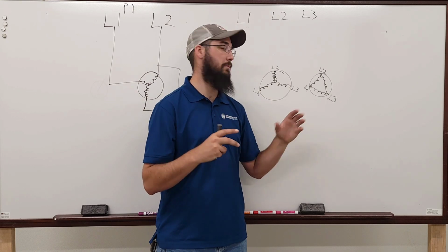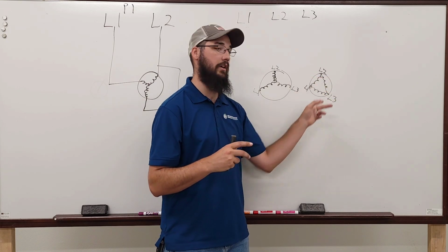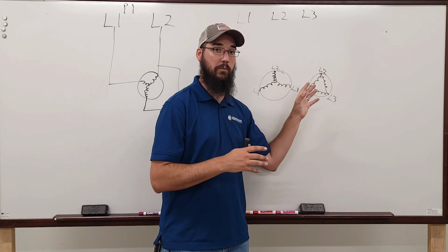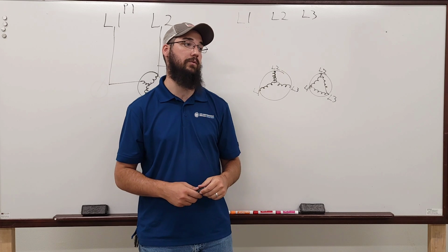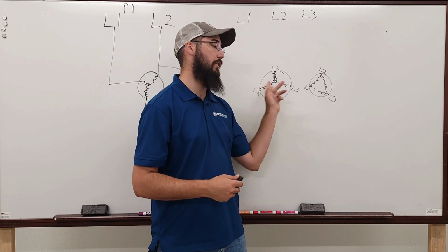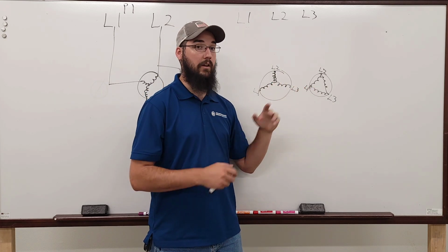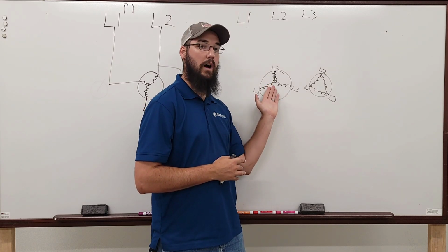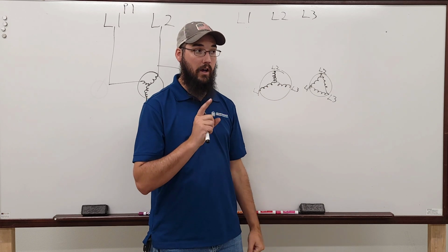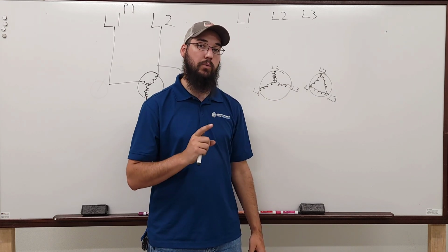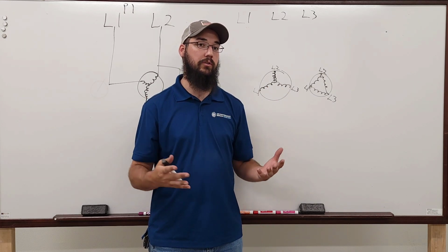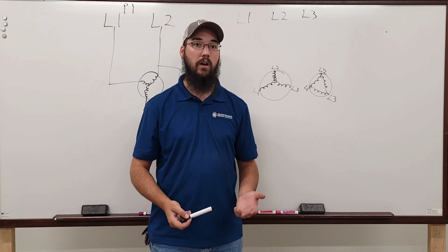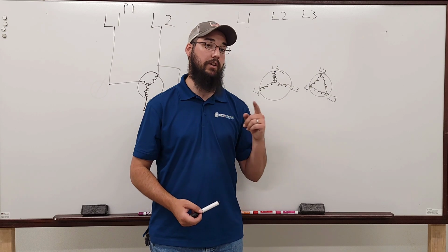So the transformer for the building is going to have, this is your delta sign, for the transformer. And you can actually walk up to the building transformer and look at it, and you'll see one of these two symbols on it. Now, like I said, every building we have that I'm aware of is going to have a Y configuration. But the majority of the motors we use on the larger horsepower, say 40, 50, 60 plus horse, are going to be a delta configuration motor.